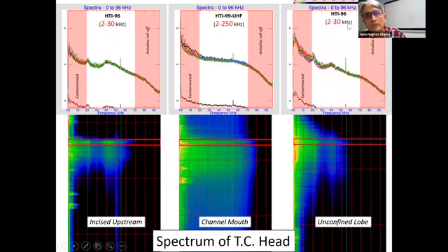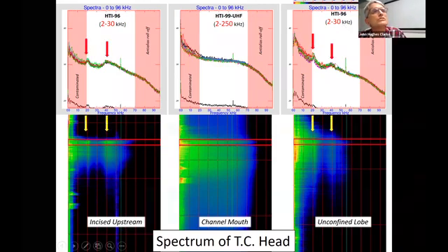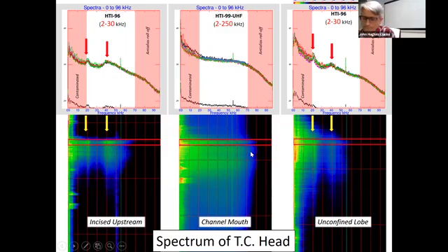I bought these cheaper hydrophones, which aren't supposed to work above 30 kilohertz, but the manufacturer says you can try, why not? And you have these secondary resonant peaks. If you look, you'll see these peaks, and you can see, sorry, dog issues. You'll see in the spectra that you've got these bright zones running through the spectra. They aren't real, they're purely a response of the hydrophone. I could try and gain that up, but unfortunately the noise comes with it. So what you can do though is pick the peaks and look at the relative slope of that spectra.